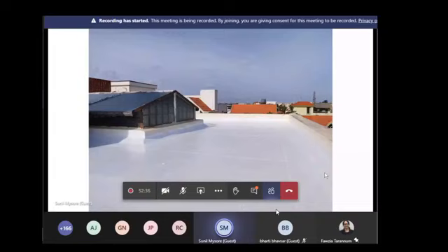Okay, so if you can get hold of the data sheet of the material that you've used on the roof, that can tell you the composition. Tomorrow, if somebody has painted it, there is no way for me to tell by visual inspection whether the roof coating is food grade quality or not. It's impossible. So if you have got anything done, better keep at least a photograph of the box, or keep the data sheet with you so that you can refer to it at any given point of time.